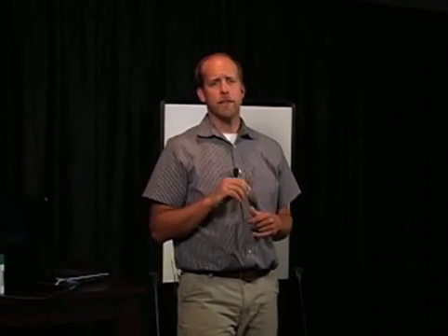Give your client mold prevention tips. Clients love tips. Moisture is the key. Keep the building clean and dry. Dry wet or damp areas within 48 hours at most. Fix leaky plumbing and leaks in the building envelope as soon as possible. Watch for condensation and wet spots. Fix the sources of moisture problems as soon as possible.